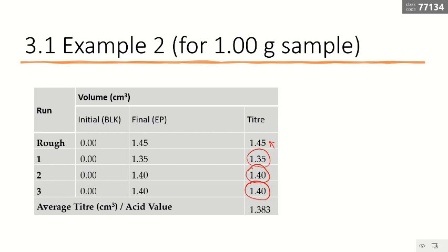So from this data, we are going to calculate our acid number of free fatty acid. Instead of using all the previous logic, I can just directly use the ending point minus the blank, which is the difference of this volume here. I can directly use it. The mass here, the big M or the smaller m, which is 1 gram of sample, we can just leave as 1. Much easier to calculate.